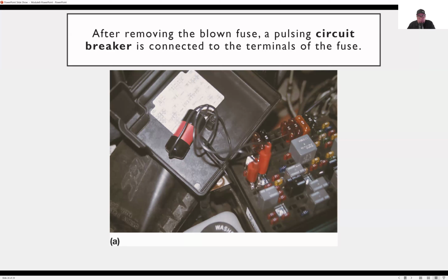So we go and we look for the fault. We think we may have it. I don't know. We try and check it. We put the circuit breaker on and boom, it pops again. Okay, we didn't find it. Keep going, keep working. You keep going until you find the fault and you repair it. And then you can verify with the circuit breaker that it works without continuously using fuses over and over again.